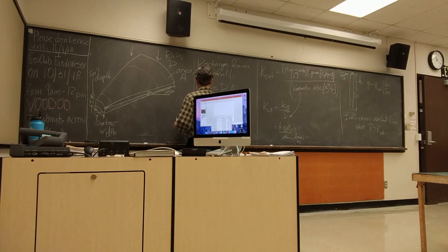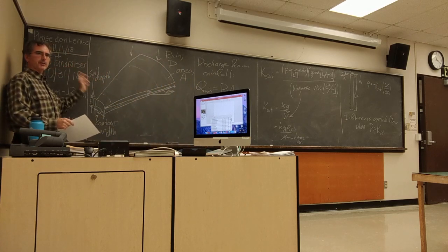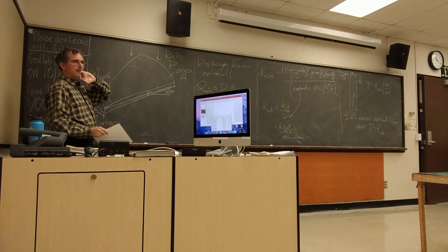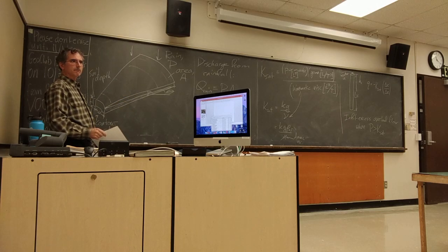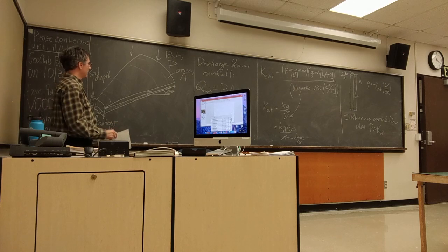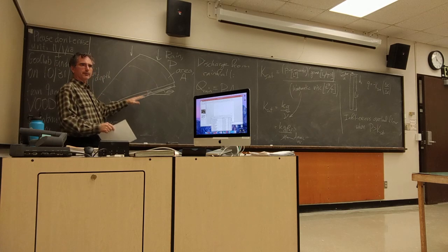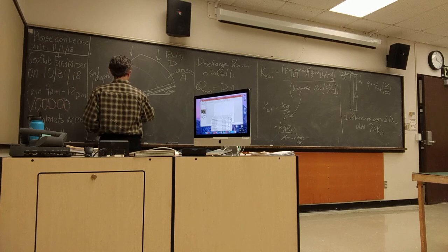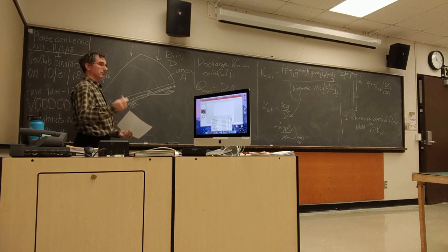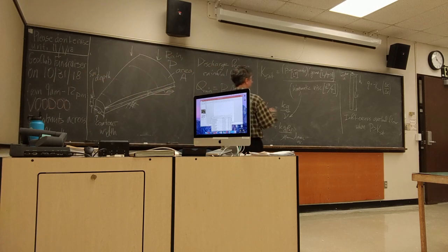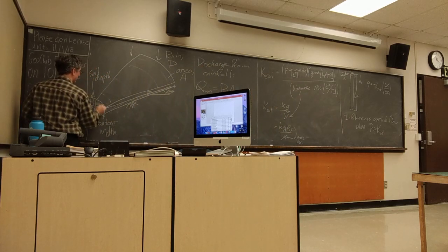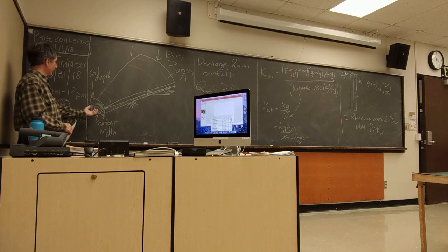From Darcy's law, the volumetric flow rate is proportional to the head gradient. What's the head gradient here? Well, I don't know exactly, but a good approximation is the topographic gradient. It's a pretty good approximation, especially if I've got a relatively uniform soil thickness over a relatively impermeable bedrock layer down here. So my head gradient is, to be precise, sine theta, the sine of the slope angle. And the volumetric flow rate: saturated hydraulic conductivity, and that was flow per cross-sectional area. The cross-sectional area is then just the total soil thickness times that contour width W.